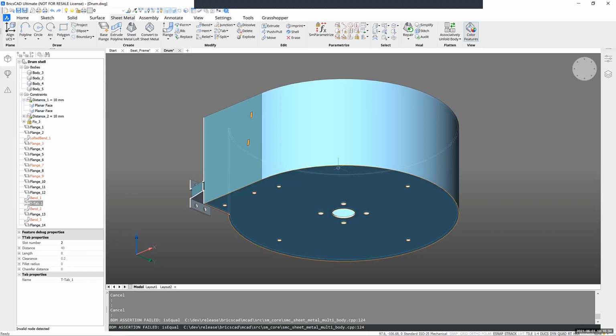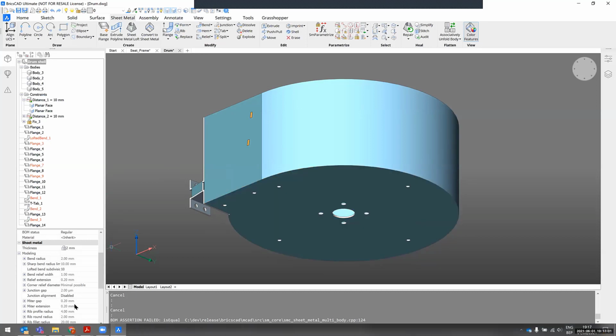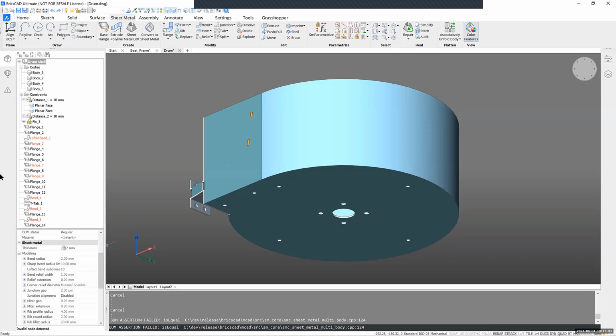If you have a curved or a banded array, you can only control the distancing with these creation values. So these will be taken upon creation, and these will be applied. And since it's a band, we don't have the functionality to create it like a feature that you can still edit. So that's why we set these values beforehand. And once we set these values, so tab slot number on 0 and the ratio under tab distance on 100, we can actually create the array tab.